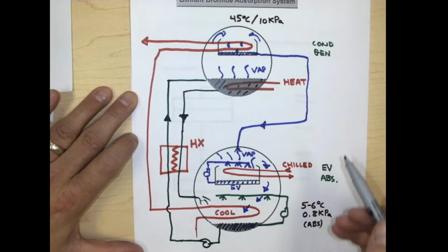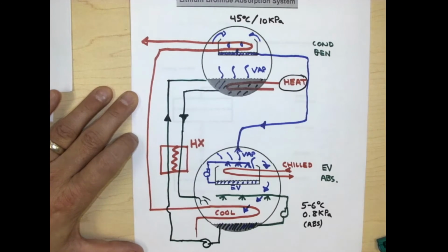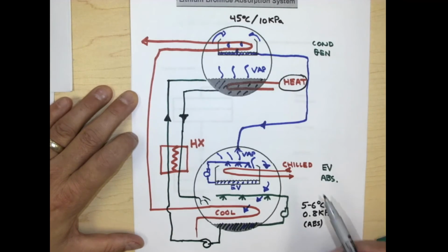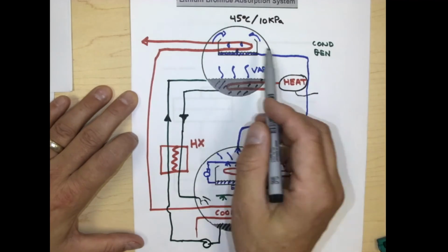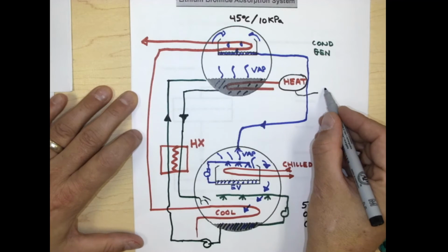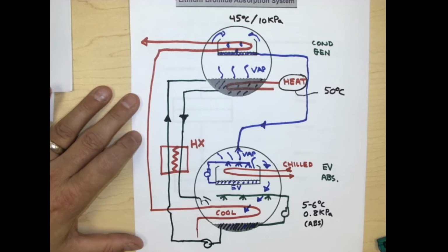The key thing is that if you're able to replace the compressor work, you can do so by adding in heat, as long as you've got an equivalent amount of heat to add into the system. And ideally, it would be something that's wasted heat. And if this thing's operating at 45 degrees, we need to have, let's say, 50 degree Celsius heat source or higher in order for this thing to run.